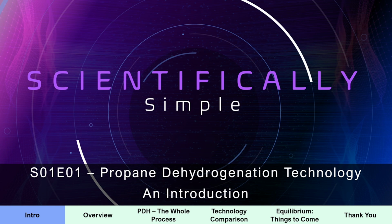Thank you, Brandon. As Brandon highlighted, propane dehydrogenation is, as the name implies, an alkane going to alkene. In this case, we have propane turning into propylene after removal of hydrogen. Historically, propane dehydrogenation has been preceded by butane dehydrogenation, which turns butane into isobutylene, which has been used to upgrade the octane number of gasoline. So, as a historical fact, it's just a continuum in that sense.